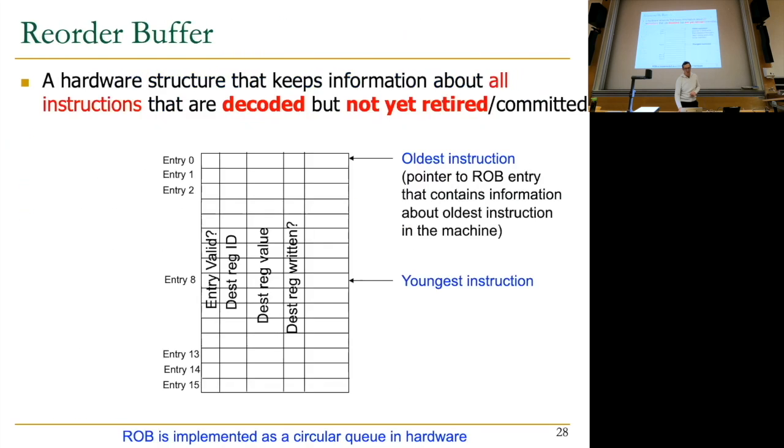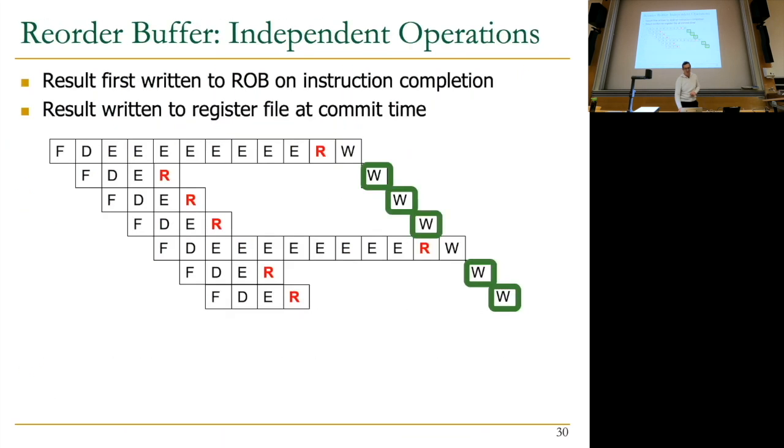Now the reorder buffer fixes the problem by decoupling the sequential execution semantics from the actual writing of the result. Writing of the result is microarchitectural. Sequential execution semantics is architectural at the end. So now this enables higher performance because we can enable reading of these values that are written by instructions, because there might be some dependent instruction. We're not showing that in this picture, but we're going to see that soon. But we have not violated the semantics either. Okay.